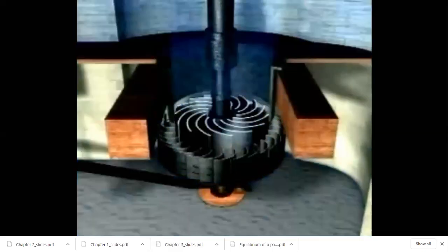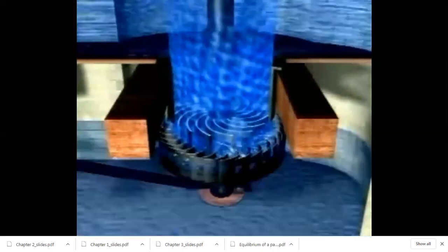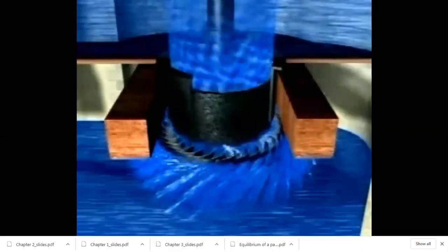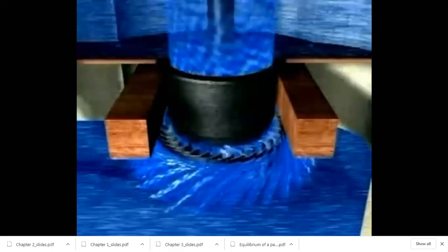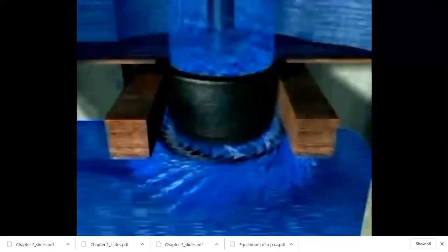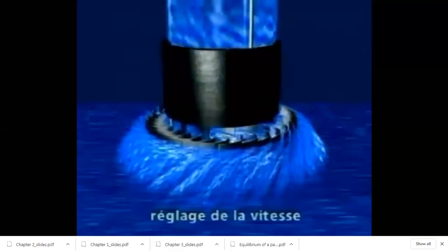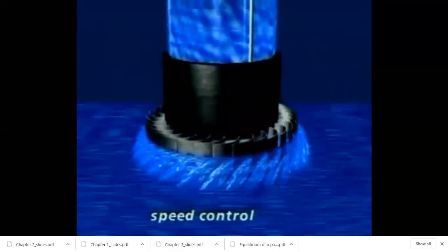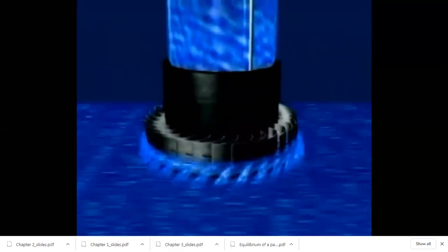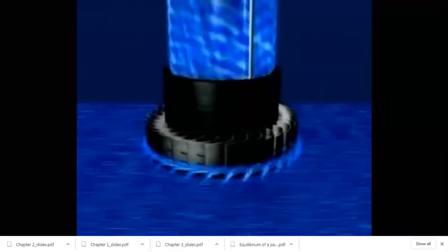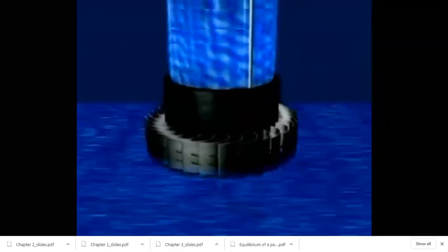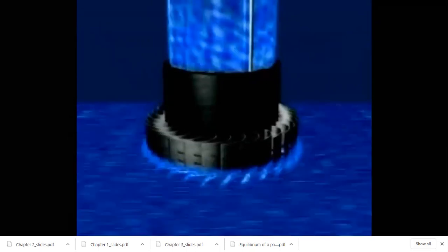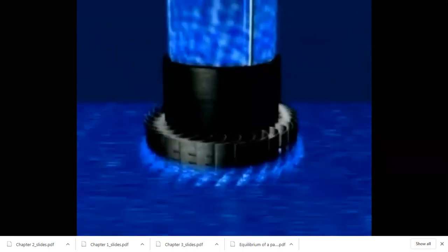And in this case, when you are moving on the moving blades, you have two effects. You have the pressure drop that will help in rotation, plus you have the conversion of kinetic energy of your flow into rotational energy. So in the moving blades, you have a double effect that will lead to the rotation of your turbine blades, which is the pressure drop over the blades plus the transformation of kinetic energy into rotational mechanical energy. In this way, we have converted the energy of the flow of jet of water into mechanical energy of rotation using this design of turbine.